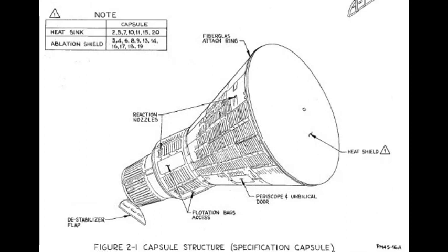The capsule is of a conventional semi-monocoque construction utilizing titanium for the primary structure. Capsule construction is designed to protect the internal cabin from excessive heating, noise, and meteorite penetration. Provisions are incorporated in the capsule to permit cabin entry, exterior viewing, and emergency exit.